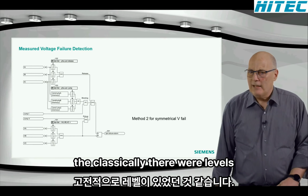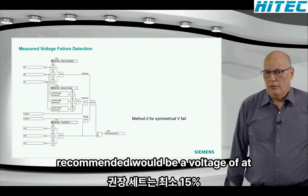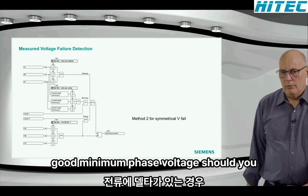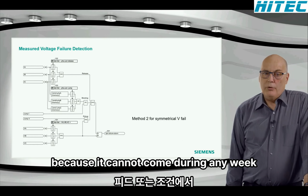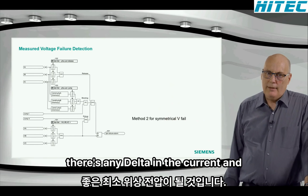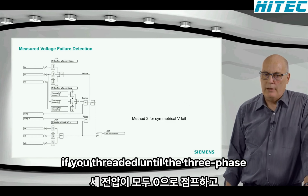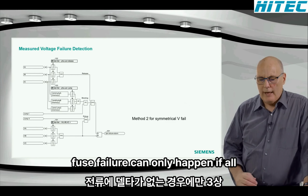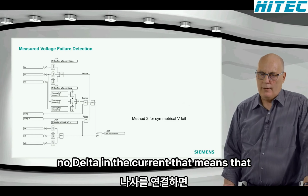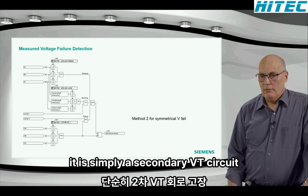I think classically there were levels of secondary voltage of 5 volt. I think the recommended setting would be a voltage of at least 15 or 20% as a good minimum phase voltage. It cannot come during any weak in-feed or other conditions, because if there's any delta in the current and it's extremely sensitive, it will not be a fuse failure. The three-phase fuse failure can only happen if all 3 voltages jump to 0 and there is no delta in the current. And that means that it is simply a secondary VT circuit failure, 3-phase.